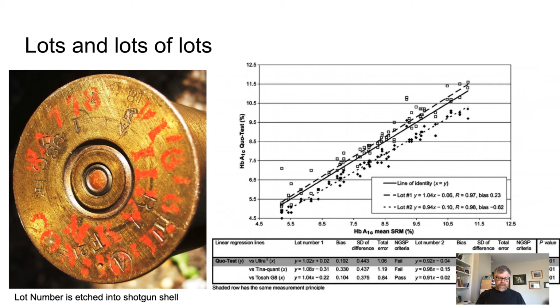So for example, let's say that you're building something and you need a bunch of 400 kilo ohm resistors or whatever. Then you buy all of the resistors that were made on the same day by the same person or the same factory or whatever, because they're all going to have exactly the same characteristics.